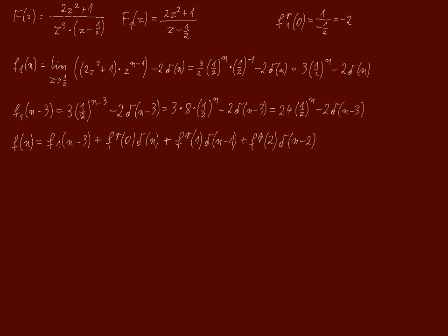Please note that the triple pole in z equal to 0 is the same as in numerator z to the power of -3, and the latter we used earlier as a delay. And indeed, it is a delay of 3 samples. But what does this do? In control, we assume that for a time less than 0, the function is equal to 0. Therefore, if a function has been delayed by 3 samples, it means that the first 3 samples, counting from 0, must be 0. Therefore, the following 3 conditions must be met.